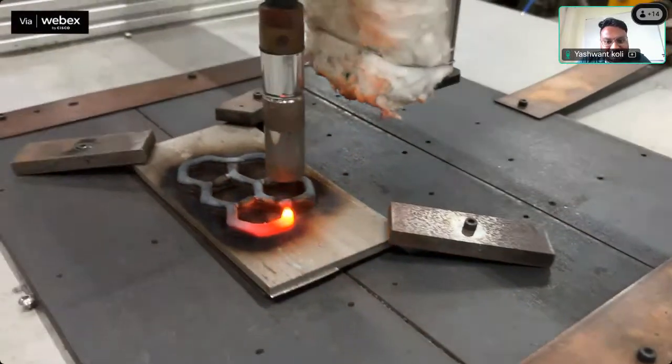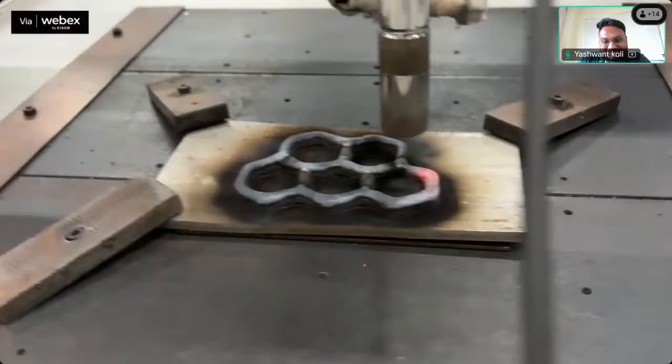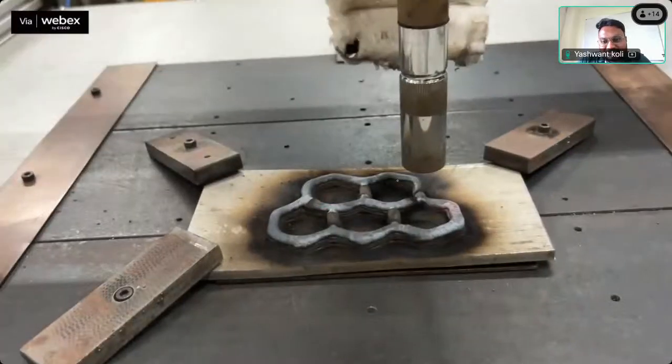Yeah, so you can see a red hot stainless steel is here. For each layer, what we are doing is we are settling it, solidifying it for 30 seconds, and then the next layer is being deposited, because we are using a thermal imaging camera, or IR camera, to check the temperature profile at this bead. So the interpass temperature should be constant throughout the building direction, as we are building from the substrate material up to the top surface. So the temperature gradient should not be mismatching, otherwise the anisotropy problem will increase.